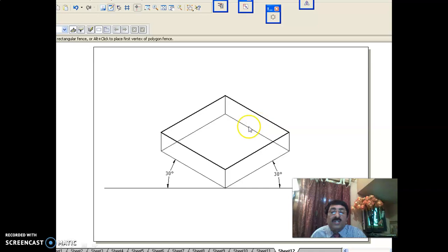Principle of isometric projection is your top surface should be seen, left surface should be seen, right surface should be seen. In that way, darken the top surface, darken the left surface, darken the right surface. Now, you are doing it by a different method. You can directly take this as 80 into 0.816, or take 80 only, this 80 only, this 20 only. Then finally, take the entire thing, scale by 0.816.